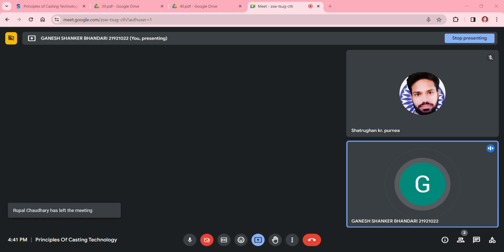When we fill the molten metal inside your mold, the riser and gating system also get filled with molten metal, and during the solidification process they also solidify with your castings. When that has solidified, you take that casting out of the sand mold. So removing those riser and gating systems or excess material, whatever we have provided during the casting process, what do we need to do?